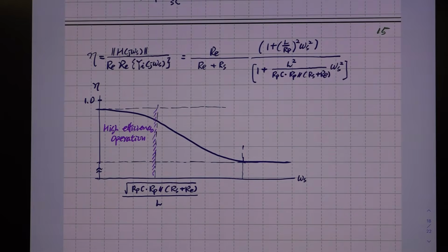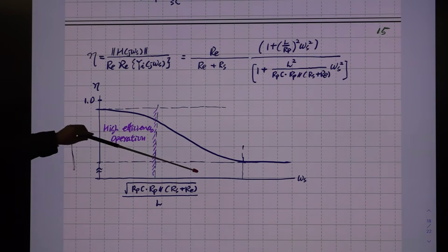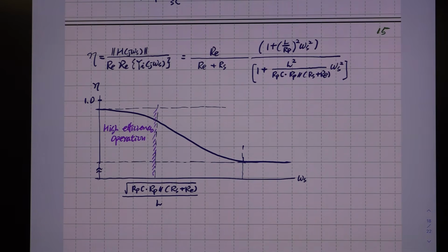So this is efficiency. This is the plot. I took this example from Erickson's draft, so that should be accurate. The maximum efficiency of that inverter is 1, obviously. But with these two parasitic resistances the curve looks like this. This is the maximum efficiency we can achieve.